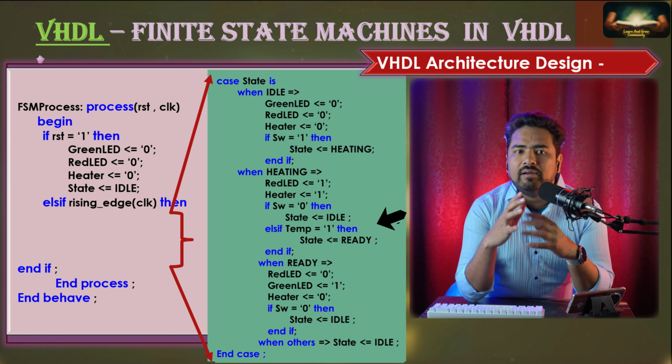So finite state machines can help you in optimal design and functionality. Always design a state machine with a registered process. This will cover your transition issues and your design will always synchronize with your clock signal. Another reason for using a register process is that a state machine requires memory, so the register process stores that state information in the flip-flops. Always give a reset condition to ensure that your state machine can return to its default state, and it will also provide a well-known starting point for your designs.